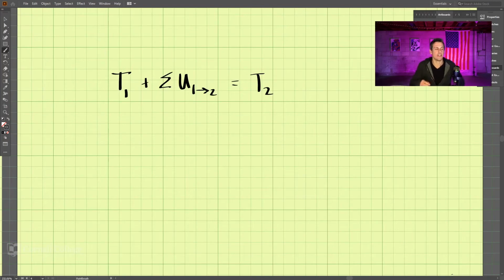Now, the conservation of energy equation that I just introduced may be making you a little nervous, because every time in the past when you've done conservation of energy, there's been a potential energy term. And in our equation, there is no potential energy term at all. So where is the potential energy in this equation? Well, we factored it into the work term. Remember, for moving the height of a weight, we said the work term is negative W times delta Y. So the potential energy that you've always seen in the past is built into this work term.